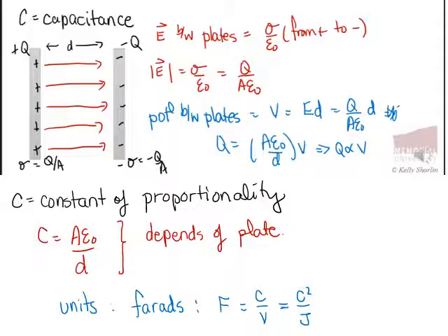So sound waves are emitted, they hit the microphone, and it vibrates a plate called a flex plate that changes the capacitance, makes a charge flow. That means that the sound waves get converted to a current that's amplified and then recorded digitally. So that's kind of an interesting application of a capacitor.